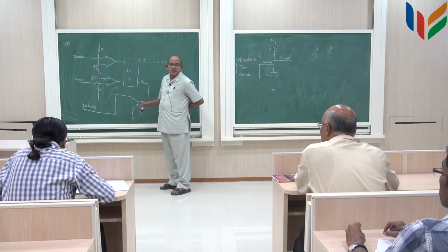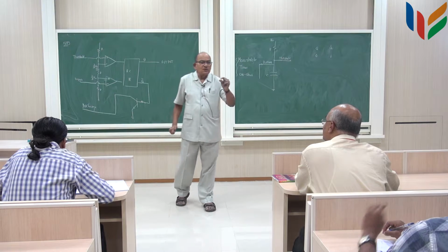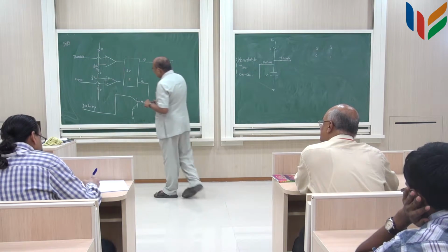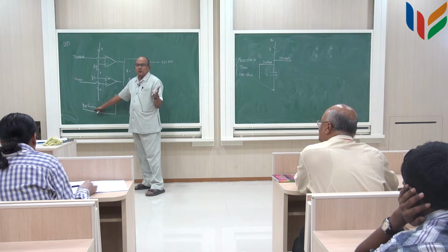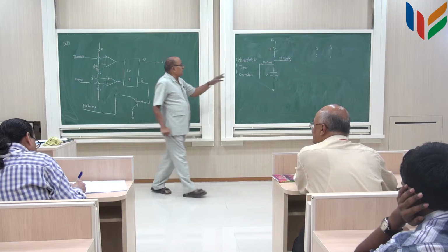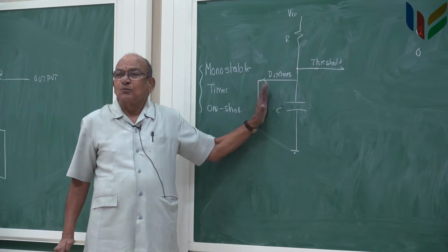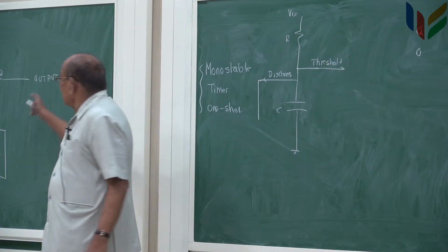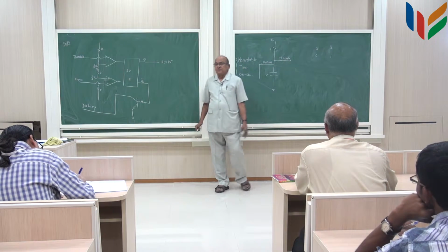So that the collector current is very large, and the voltage across the transistor will become very small. So this is the saturated condition. Once in saturated condition, the discharge terminal will be at almost ground potential. So this capacitor initially sits at ground potential, because of the configuration of this being 0 and that being 1.